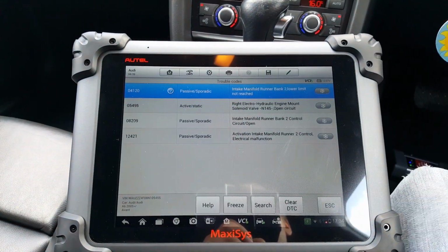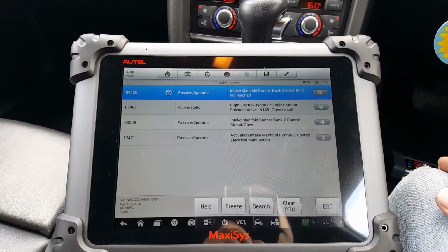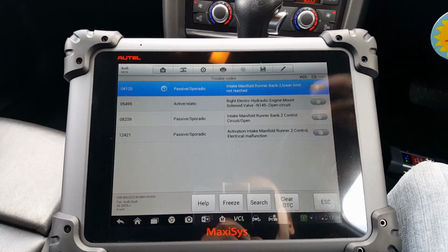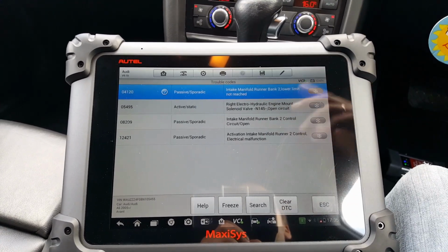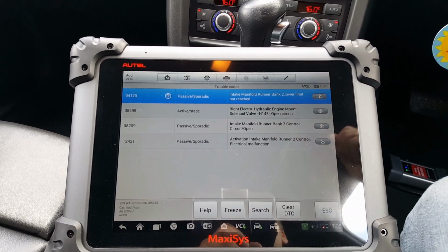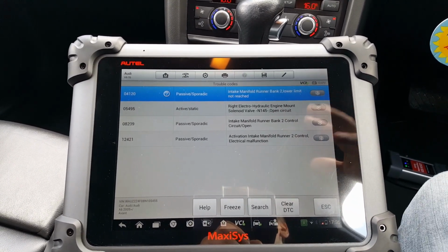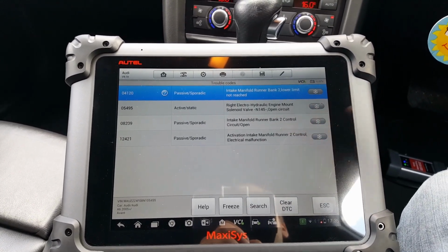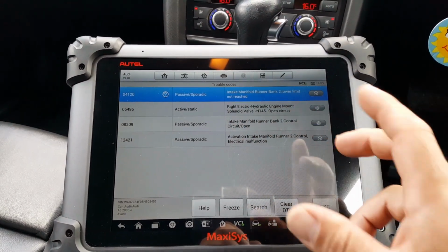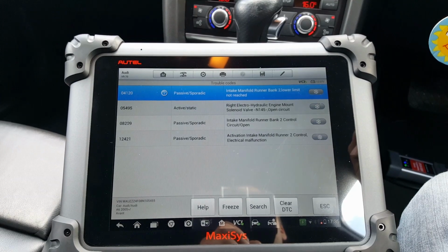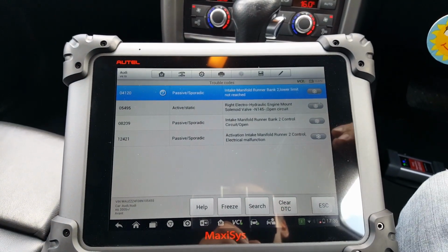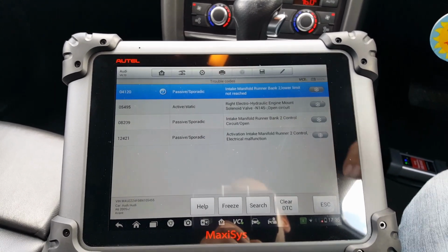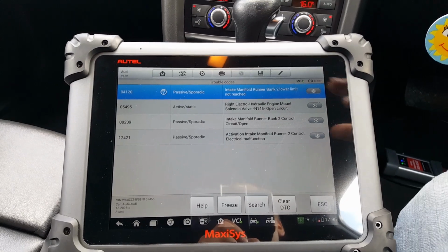And the way I've done it is, well, let me tell you first, because I'm on my own now, I had to ask the missus to come and cycle the ignition. But basically, what it does every time you turn the ignition, both actuators on both sides, they move. They move all the way to the lower limit, and then they come back to their original position.